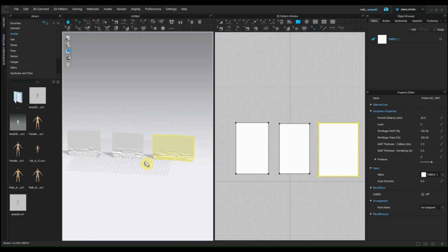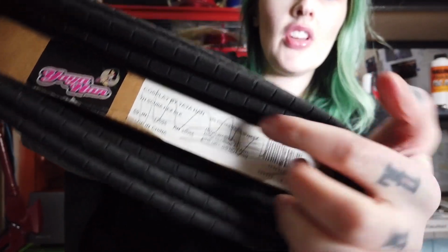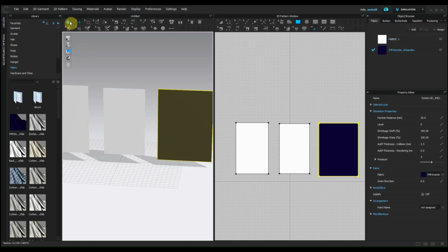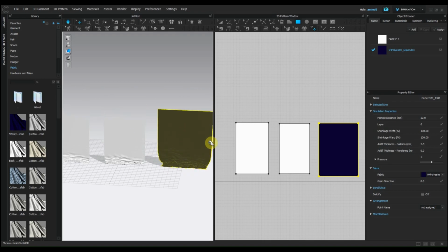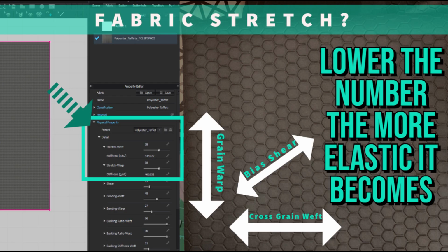When you buy a fabric, it usually says on the end of the fabric what the material is. So this Yaya Han says that it is 94% polyester and 6% spandex. So you just come into your fabric selection over here in Clo3D and you pick the pattern that has that same property. If your fabric does not exist, you can actually come into this physical property window and change the material or how stuff moves. So when we apply this spandex, you notice that when we run the simulation, this piece of fabric falls differently than a piece of cotton or a piece of silk would.